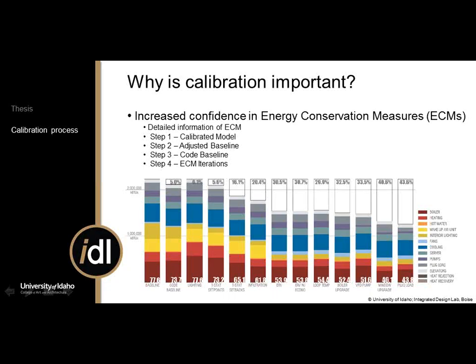The biggest example of that would be if you're trying to calibrate a building that's 50% occupied. But when you're doing the investment analysis, you might want to know how much energy you're going to save if that building ramps back up to 90-95%, right? So you would adjust your calibrated baseline towards whatever baseline condition you're doing, and then you're able to actually go through and test these different measures against it.